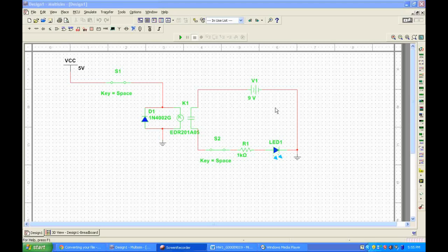So basically the way this side of the circuit works is that once the relay opens and we can get current flow through the whole circuit, we have a current that's generated from the power supply here that runs through the LED, and the LED lights. So the reason I use 9-volt with a 1 kilo ohm is because the LED requires a minimum of a 5 milliamp current in order to activate. So when we have a 9-volt power supply with a 1 kilo ohm resistor, that gives us 9 milliamps. So that's plenty to power that LED.